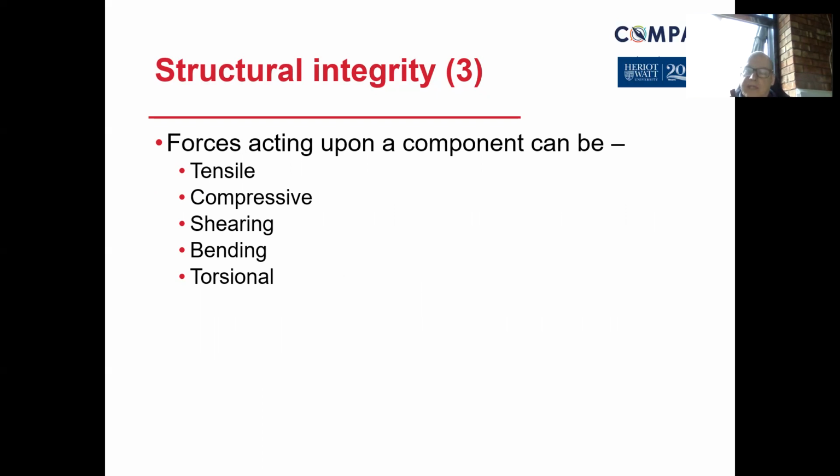Hence, when you do use it for lifting equipment, it indicates the limitations of the weakest part of that particular lifting equipment. So you might have an overhead crane, gantry truck crane, that's capable of lifting 5 tons or even more, and it's got that written down as the safe working load. But then you've got the hoist that's connected to it, may be limited to carrying 1 ton, and then you might have the hook or maybe a shackle that's attached to the hook or the chain, and you look at the information and it's limited there to say 1/4 of a ton.